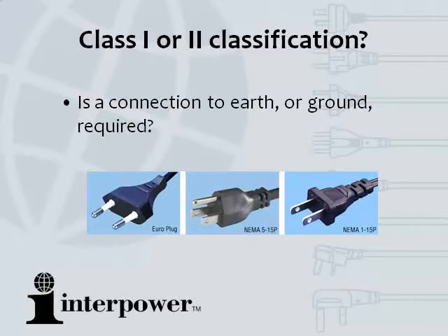In the UK, where an earth pin is required to allow the shutters in the socket to open, this third pin is a non-connected dummy in Class 2 plugs. Class 2 plugs will always be assembled to 2-core cable, and if a moulded IEC connector is present, it will be a 2-pin female connection.